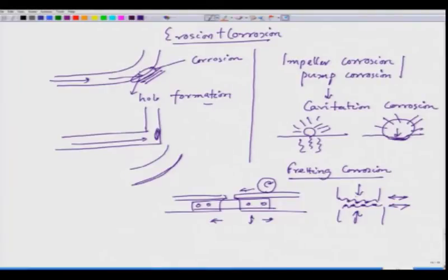So, a kind of erosion or wear is taking place. And now, once the train goes out, they might get oxidized because the temperature also goes up. So, now you can have oxidation first and then erosion, or erosion first and then oxidation. Finally, you would see that in these small dips, there could be a possibility of debris accumulation. Those debris will act further during the next fretting action when the train moves.